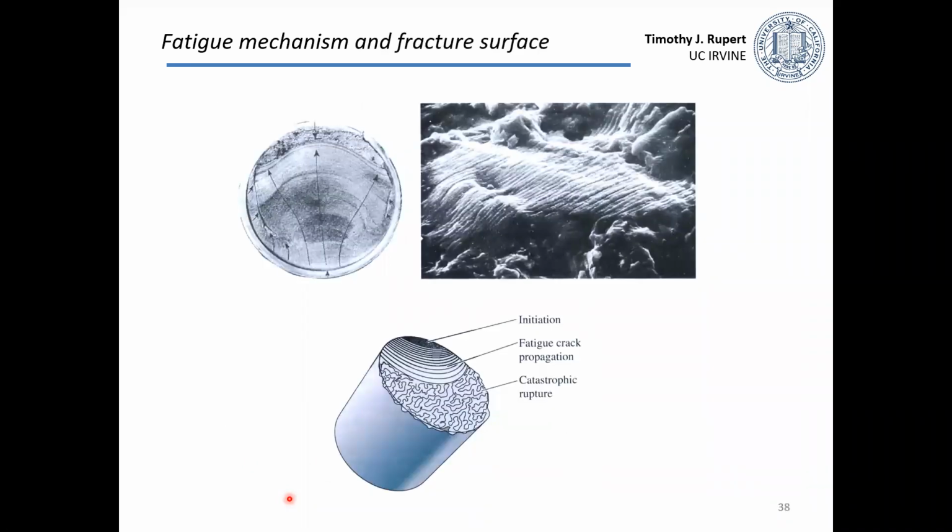You can see evidence of this on these crack surfaces. Before, when we looked at a crack surface, we saw crack start and then all these long fracture surfaces. Now there's a lot more nuance in this picture. Right here, what happened is the crack nucleated, grew, and then fractured. I'm sorry, I have this upside down. The crack nucleated here. It grew gradually as you went this way, and eventually got so large that fast fracture happened. I apologize, these two pictures are flipped.